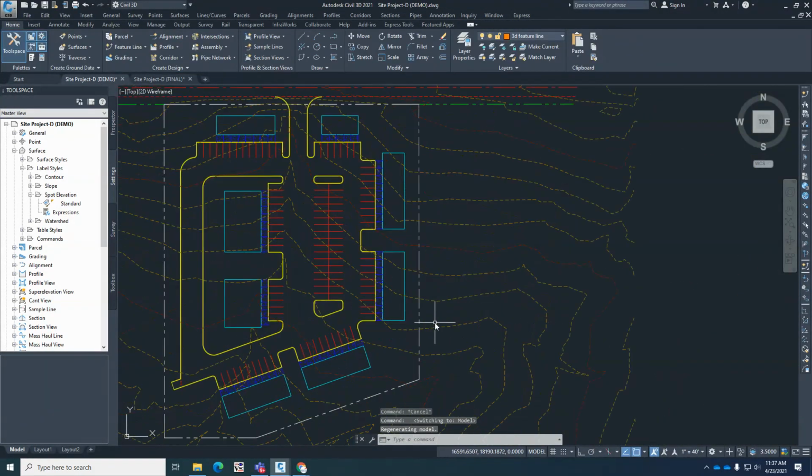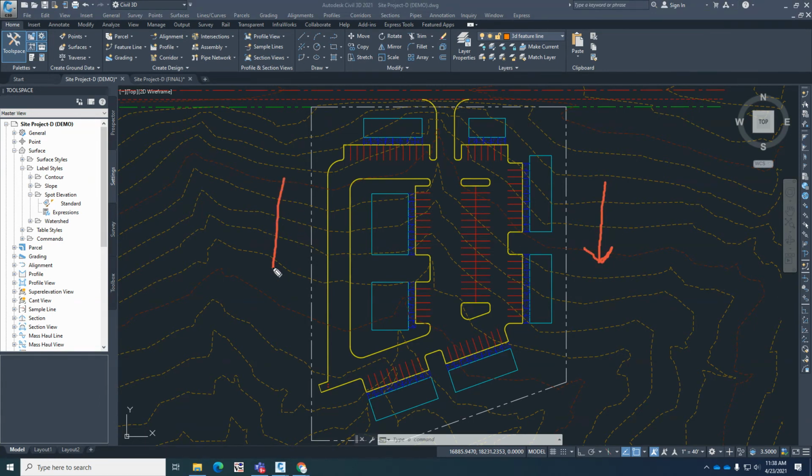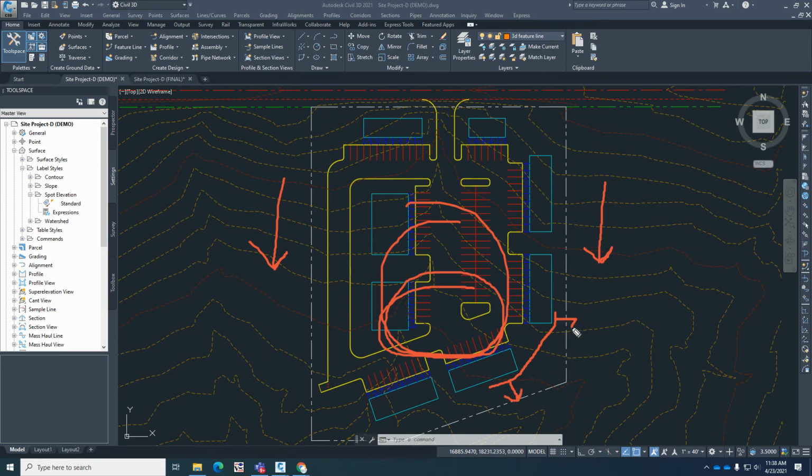It is your final project, and just make sure you do everything we need to do. Oh, one last thing I will mention, because this site is sloping fairly dramatically compared to our 5% maximum, we are going to have quite a bit of fill. This whole area, really most of the site, will be a lot of fill, meaning this area too, once you daylight the edge of the bench, you're going to have some pretty big slopes. If and when you have some pretty big slopes, that's going to be okay. It's going to be understood, okay?